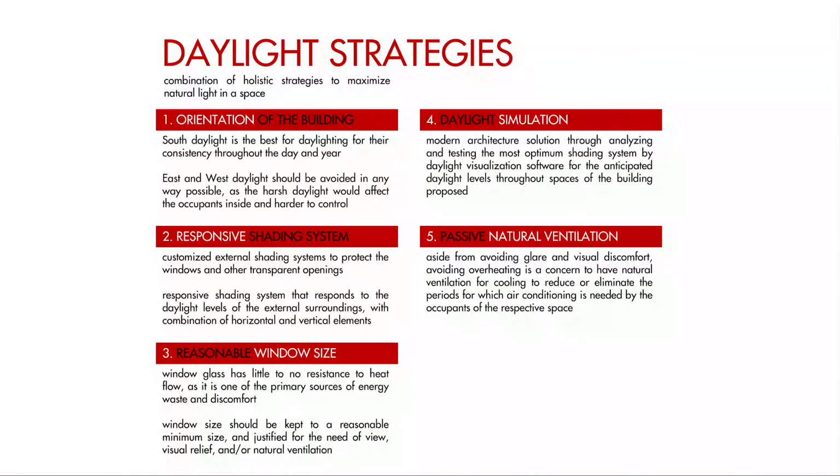In order to achieve those research objectives, I have identified 5 daylight strategies that are going to be implemented. First, the orientation of the building, in which to avoid the east and west direct daylight onto the building. Number 2, by using a responsive shading system, customizing the external facade system to protect the building that responds to the daylight levels in Punggol.